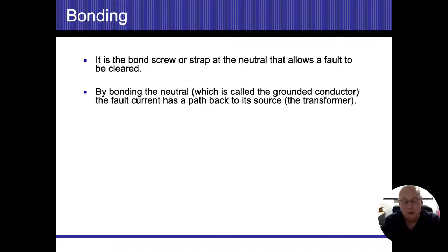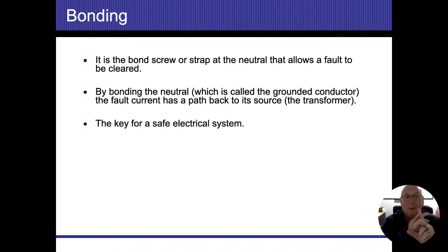After that, the next thing I'm going to be looking for is my grounding electrode conductor, all right, or my GEC. That is also known as my ground wire, but that's a specific ground wire, all right. That's going to go from the location where the bond is to wherever I'm going to be grounding this to. So whether it's a ground rod, whether it's a water pipe, ground ring, UFER ground, ground plate, well water pipe going in there, whatever I'm grounding my house to, that GEC is my connection from the main disconnect to whatever I'm grounding to.